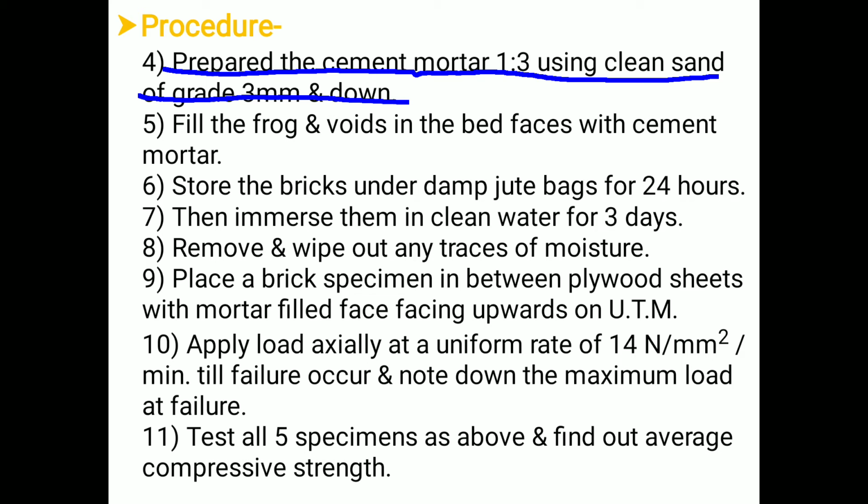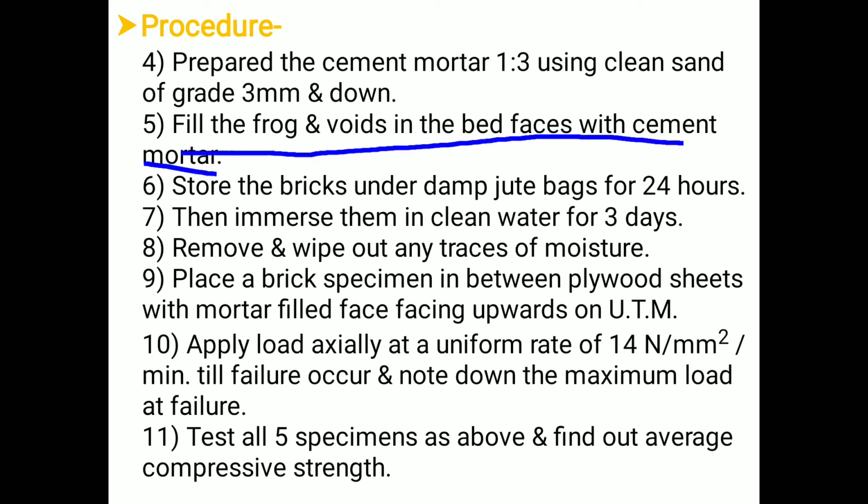The size of the sand is 3 mm or less than 3 mm. After preparing the mortar, we have to fill the frog and voids in the bed faces with the cement mortar. All of you know what a frog is.